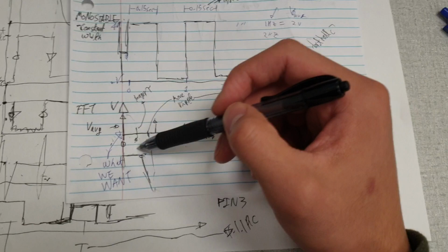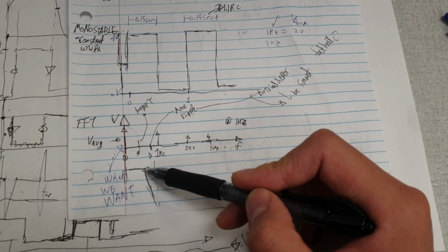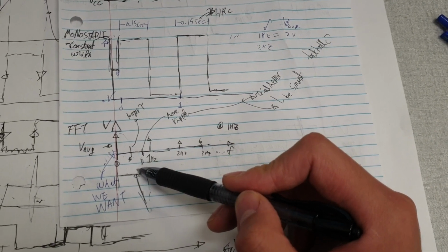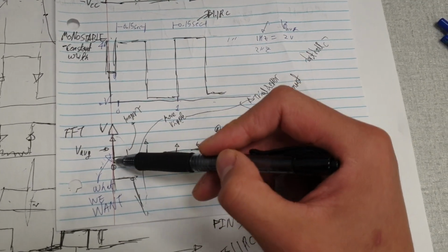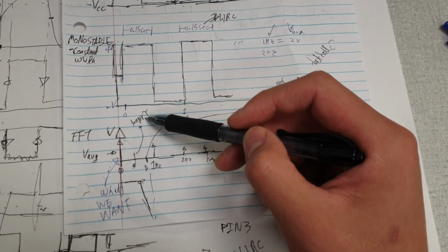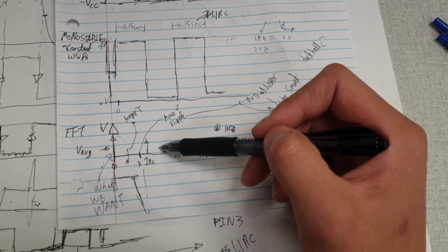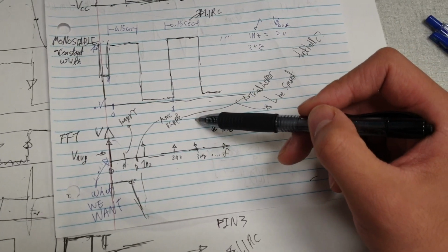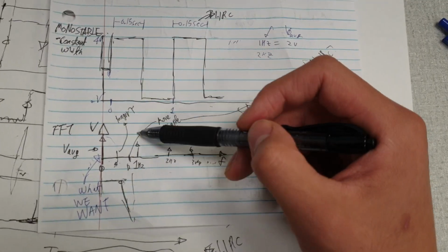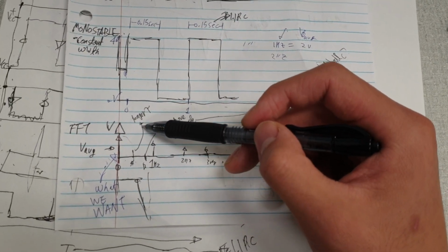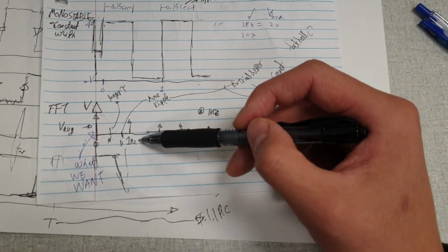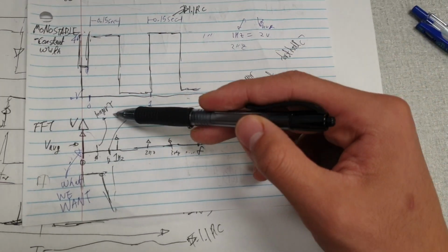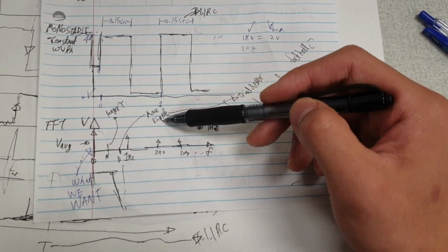And the trade we make in determining the location of the 3 decibel frequency is, if you go to the left, we get a longer time constant and less ripple. The more left you go, we'll have a longer time constant. The more right you go, you will have more ripple. So it's a trade we make between the time constant and the ripple.